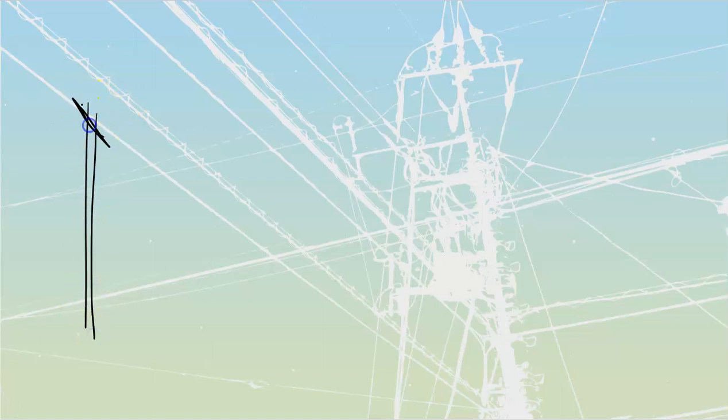So we'll start out over here at my pole line. I've got high voltage lines that are going to be coming in. Those high voltage lines, I'm going to take them down to a pole top mounted transformer over here. And then from that pole top mounted transformer, I'm going to feed over to an installation. We'll just draw out an installation over here with a weatherhead on the side. Let's take a meter base like that. And then we will feed in from the meter base and take that into a fusible disconnect.